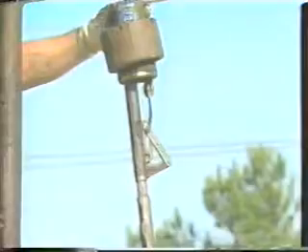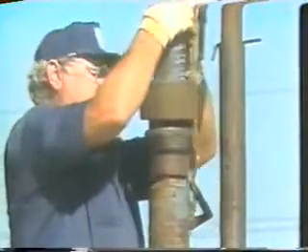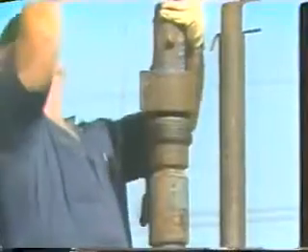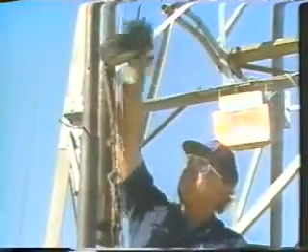The slack left in the wireline is reeled onto the reel of the wireline unit, and the clamp is removed from the wire. The tool string may now be lowered out of the open lower end of the lubricator and the proper tool attached to the bottom of the tool string. After attaching the proper tool, the tool string is pulled up into the lubricator and the lubricator attached to the wireline valve. Before opening the valve on the tree to begin wireline operations, the entire lubricator stack should be tested. If any leak is detected during the test procedure, wireline operation should not be begun until the source of the leak is identified and corrected.